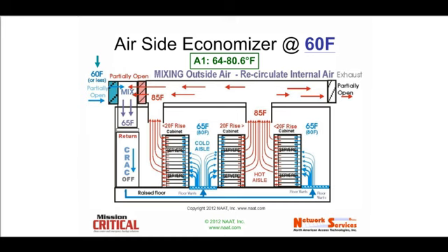So now we've got a blended air coming in at approximately 65 degrees into the floor, and, of course, now we have a 65-degree bottom to our cold aisle. Again, we're showing a 20-degree temperature rise, which means we've got 85-degree air up in the vents, and we're partially exhausting some of that to make sure we have a balanced airflow.